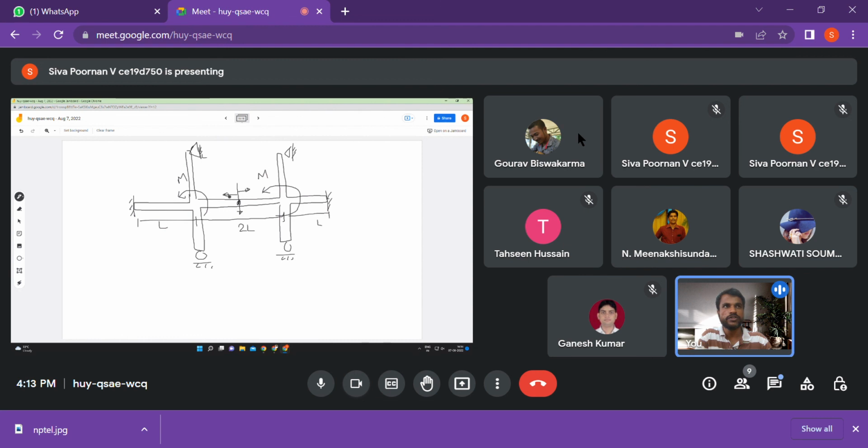And also it cannot rotate. That means the beam cannot have a rotation, because if it is clockwise or anti-clockwise, why clockwise or anti-clockwise, both sides look the same, right? So it should have a zero slope at this point. So the beam should look something like this after deflection. I'm not worried here about what is happening elsewhere, I'm just saying at this point the rotation is zero, and at this point only vertical displacement can happen. That's the point that I'm trying to show here. And that means what is the effective boundary condition at this point? Can someone say? We had just discussed what this should be taken as.